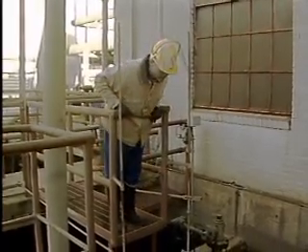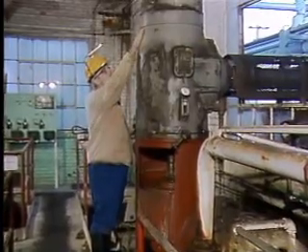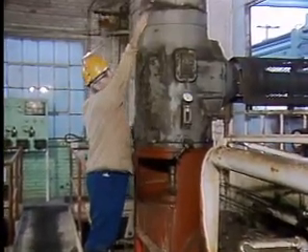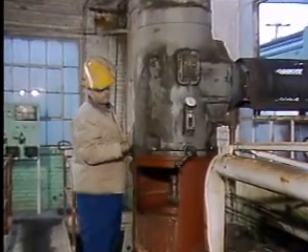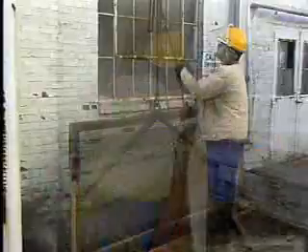While checking the water level in the catch basin, operators should also check the appearance of the water. If the cooling water is murky or if it has a film on it, there may be a problem with the cooling water system, such as a leak in one of the heat exchangers. The pump and its driver should be checked for unusual noises, excessive vibration, and overheating. The lubrication of the driver and pump should be checked as well.